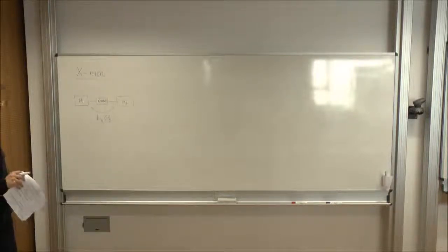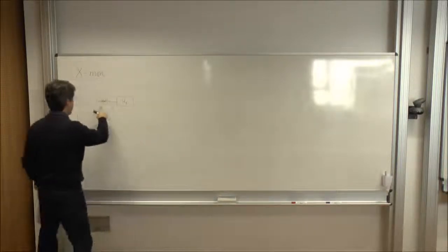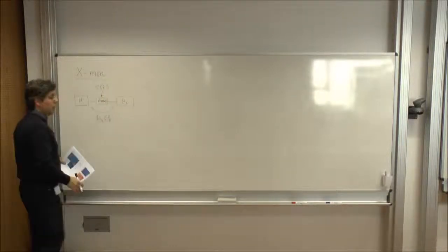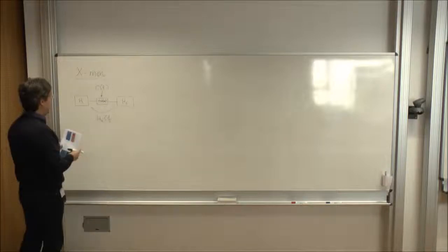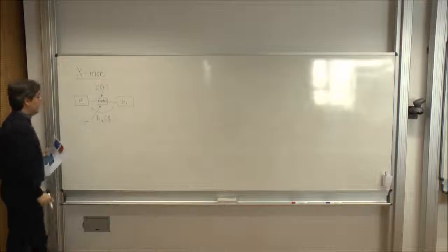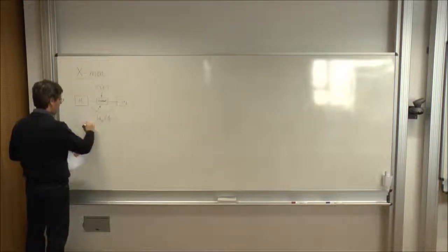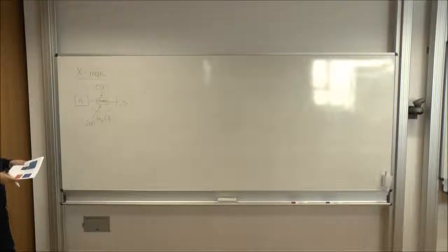So one thing that you cannot do, of course, well, it would be a bit crazy, is to expect this mediator be a tunable capacitance. Capacitance is a geometric concept, depends on the separation between materials, and it's something that is hard to tune. So the coupling has to be inductive in some way. So we have to tune basically some inductance to allow for a control interaction between electrical circuits.